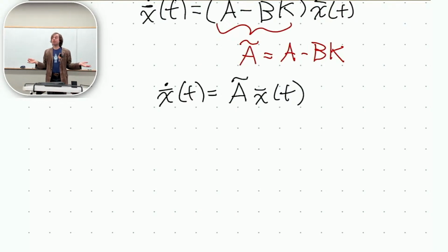Okay? In fact, there are lots of cool methods. There's one where you can say, hey, these are the eigenvalues that I want for my system. I want them all to be negative. So when they have negative real parts, I want them to be -1, -2, -3. Give me the k. MATLAB can do that. Not just MATLAB. There's a method. This method is called pole placement.